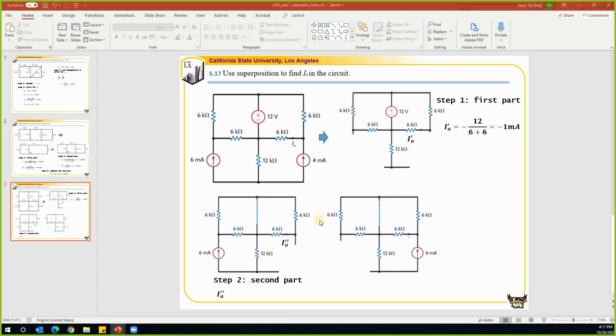So let's look at the circuit. What happened to these two resistors? Are they connected to the same node? Yes, they're connected to the same node. It means that there is one node here, it sticks out with one resistor, in series with another resistor, then connected back to the same node. And this is shorted, right? So if it's shorted, there won't be any current going through this branch, because all the current will go through the wire. The wire has no resistance. If the wire has no resistance, it will go through the wire, it won't bother to come through the resistors.